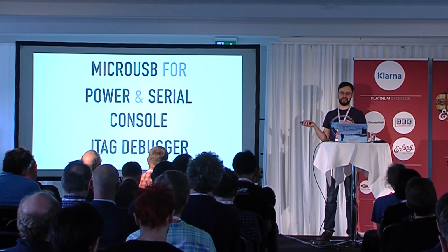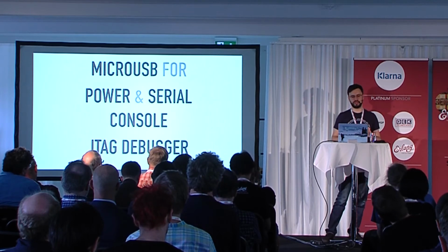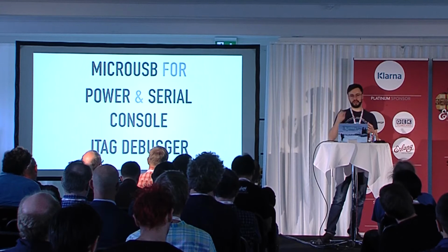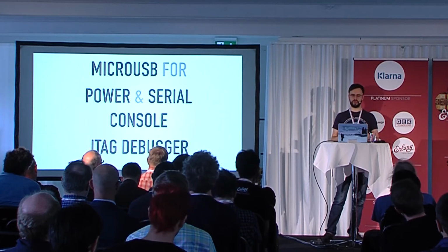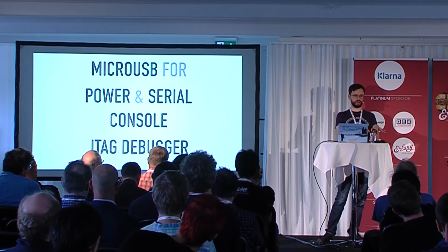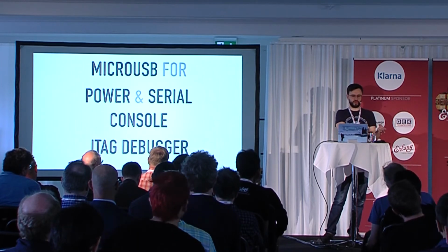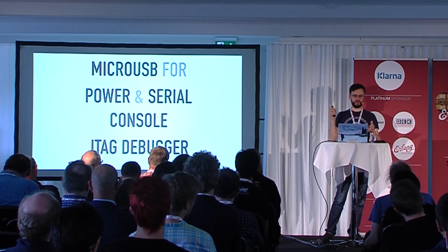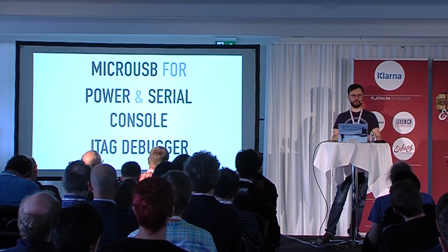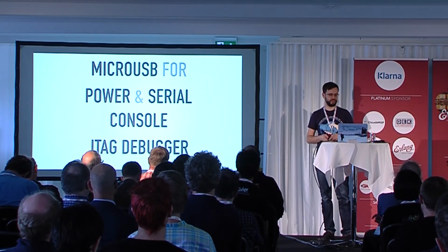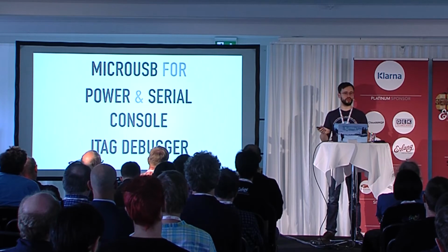And also we have this external JTAG connector, which is a standard ARM 2x10 pins, where you can connect a hardware JTAG debugger, and you can do cool stuff like actually step the processor, so you can freeze the whole system. And you don't have to change your software, because all of those features are in the processor themselves. So you connect the debugger and you can step through your whole system like a step debugger for normal languages, which is pretty neat. So it's useful for developing low-level hardware stuff.